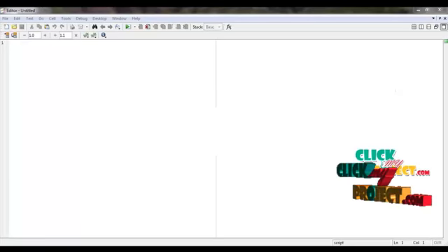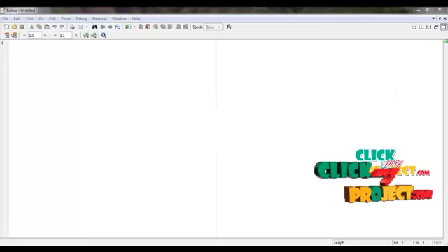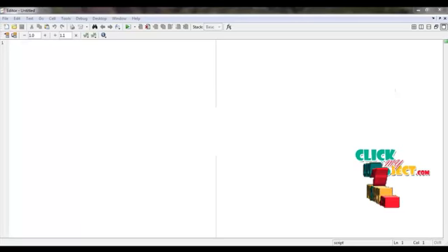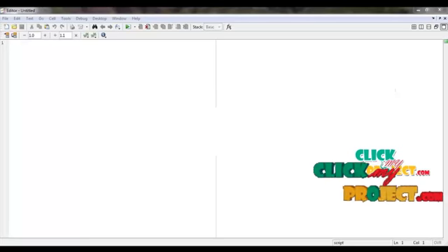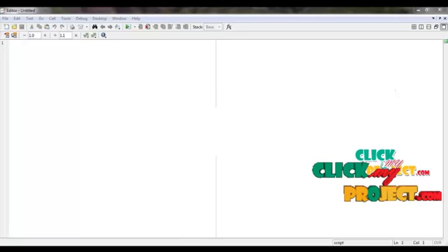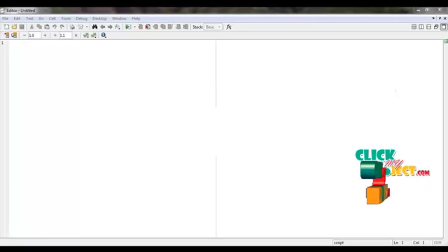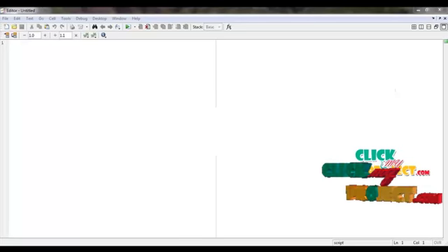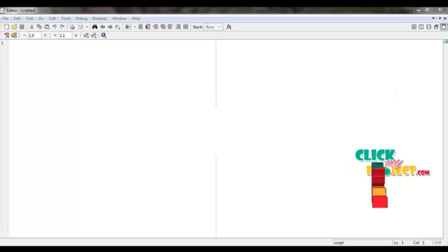Here the 4 inputs go to the torque flux calculator and also the flux sector seeker under the switching table. The torque and flux go to the flux and torque hysteresis. It finds the frequency of the induction motor by the specific region frequency of the inverter, and the current and voltage are used to calculate the torque and the flux, and the flux angle will be found. The flux sector seeker generates the 6-phase vector for generating the pulses. The pulses are generated by using the switching table.